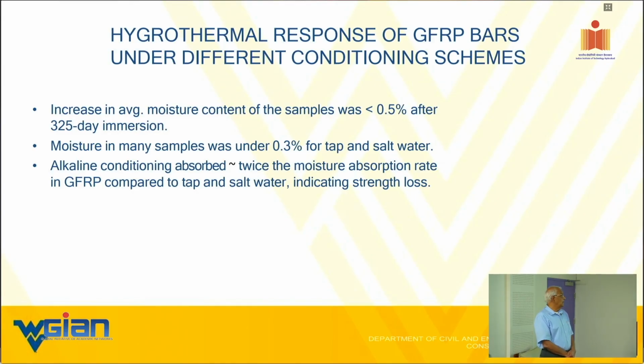But the bugbear is alkali condition absorbed twice the moisture. Why? Because the ASR, alkali silica reaction, is taking place already when you look at the moisture absorption.